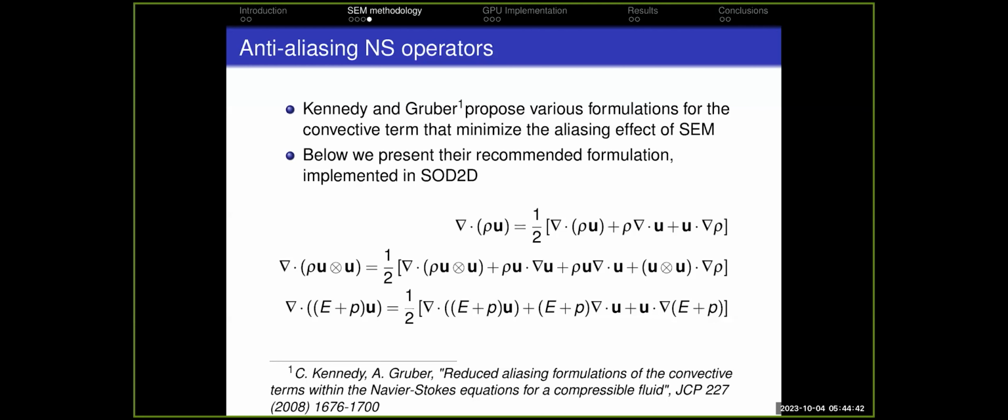So in other words, we do not need to scale the P order up to more than 8 just to compensate for aliasing. We are actually able to run with P3 and P4 elements without spurious oscillations on the flow fields, which helps diminish the elemental computations quite a bit.